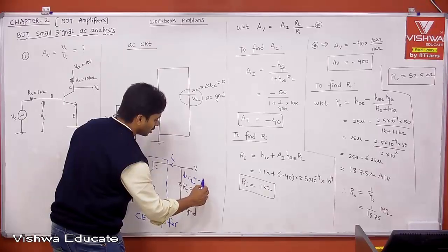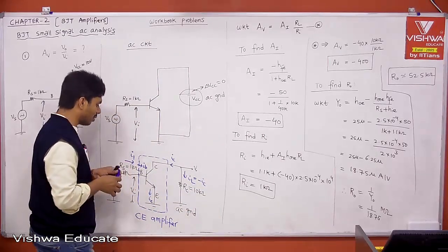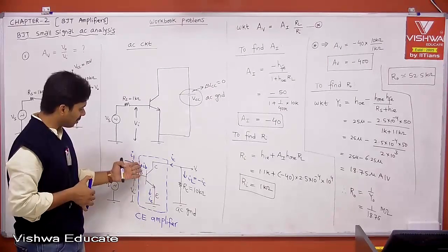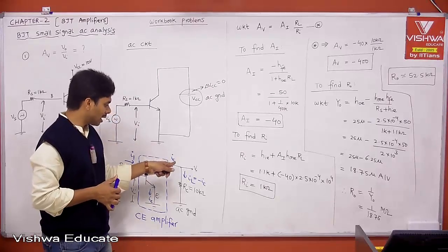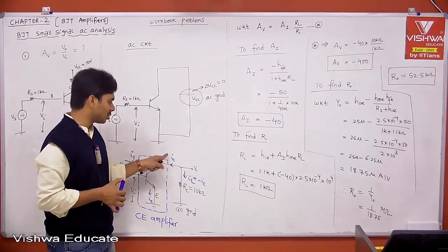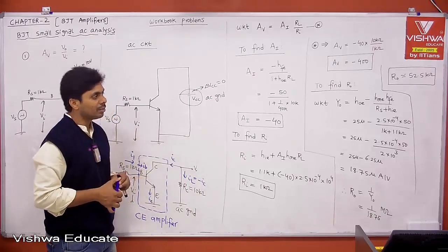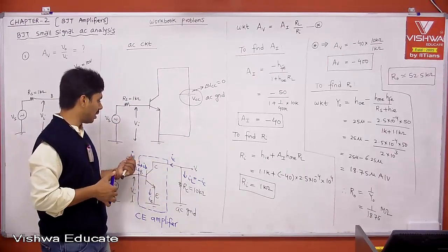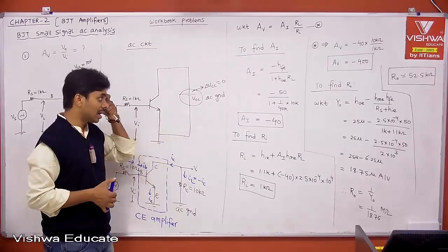Your load current is opposite to real current flow, and your input current is the same as your base current. Therefore, your two-port network input current flow is the same as the real current flow, which is IB. That is fine. But the two-port network output current, I2, matches the real current flow, while with respect to the load current, it is exactly opposite. But we took our current gain as IL divided by I1.